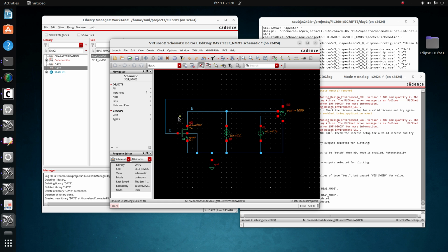So it consists of the transistor under test, which is basically sized with variables, and then we have a current that is also dimensioned with a variable. This current is going to be connected to the drain. Okay, and next we have a voltage source. This is the source, and this one is connected to a voltage controlled voltage source.